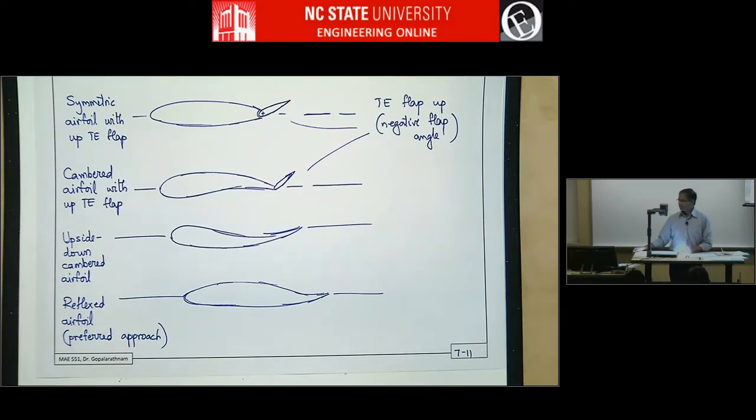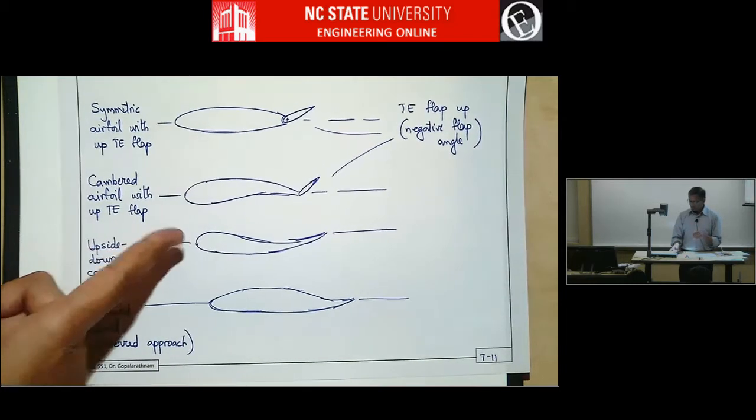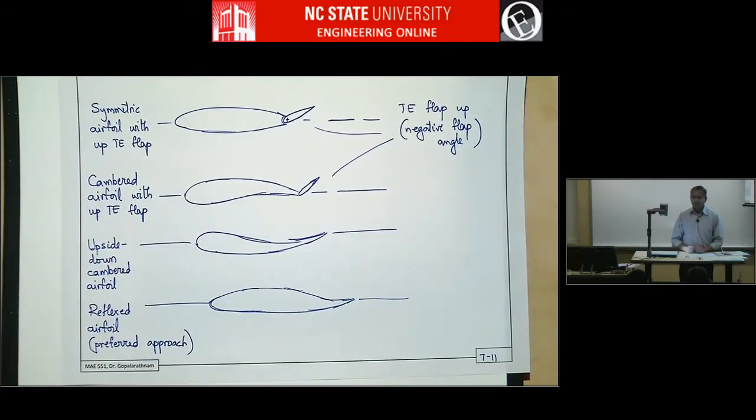My guess about what happened is that if an airplane is not in equilibrium, you can't fly it, right? Stability, if you don't have it, you can manage, but equilibrium you just have to have. Otherwise it's going to go nose down like this or nose up like this or something. So my guess is the CG was more or less in front of the quarter chord of the wing, and instinctively when he turned it upside down, it became a stable sort of flying wing.